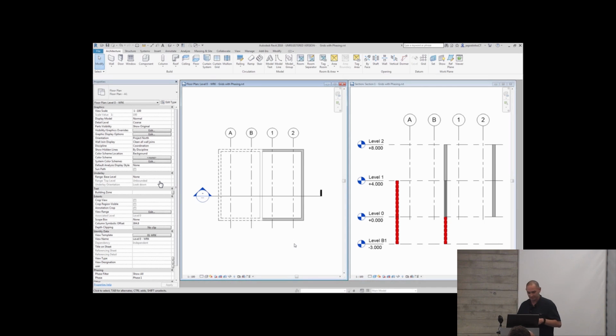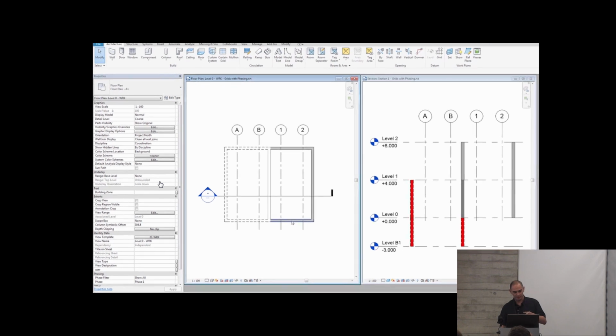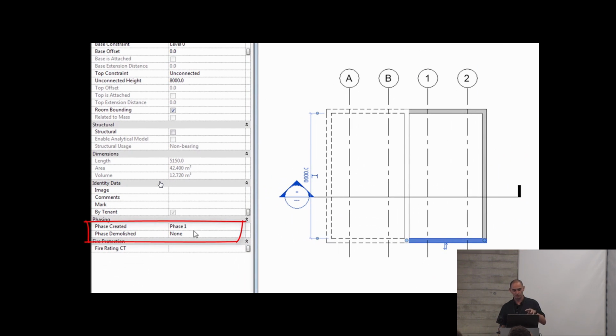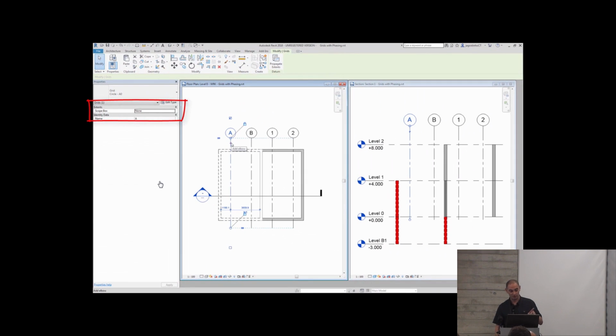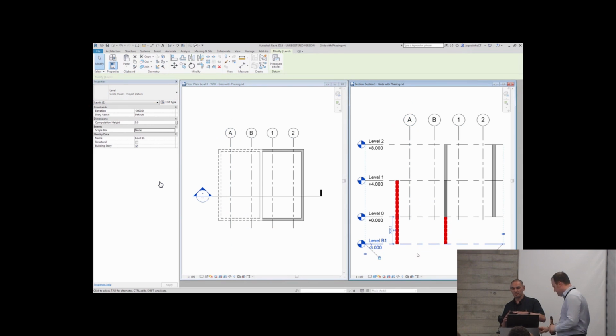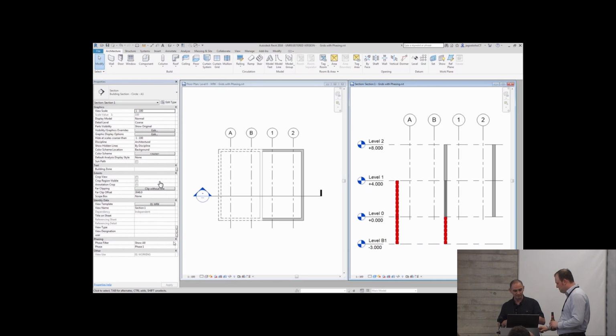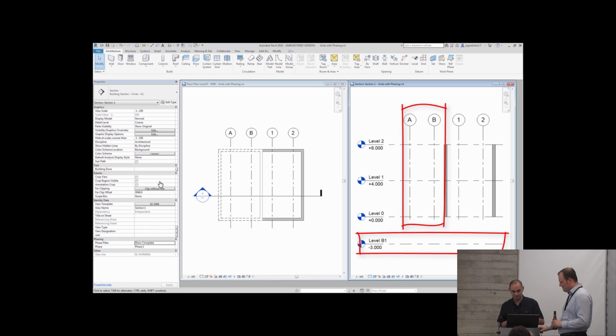From the start, right? Okay, so grid is phasing. It's just a workaround. So in Revit, you can select some elements and choose the phase created and demolished for each one, which works quite well considering that it's Revit, right? However, for grids and levels, meaning datum levels, the option is not quite available. So here's the workaround on one way of how you could do it.